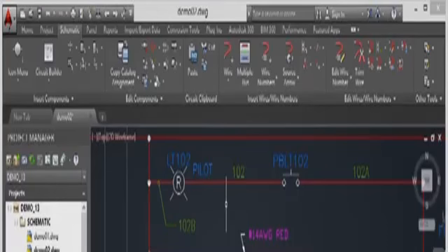Sometimes you can make a mistake and hide an attribute that you need. Typical example is the power on attribute here. If I go and hit that on attribute and hide it, all it tells me is that is a power light. It doesn't tell me whether the power is on or off. The light might be on to tell me that the power is off. It might be a warning light, for example.